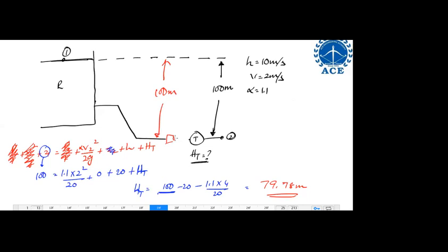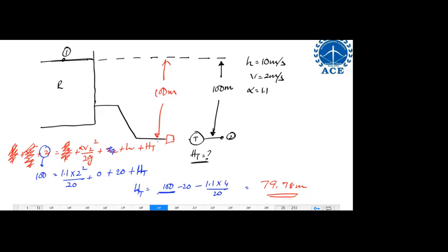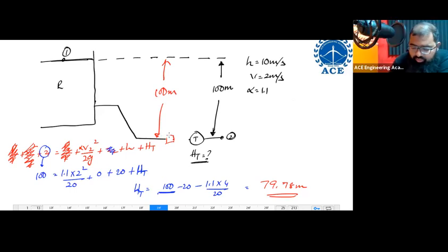Yes, sir. That is fine, accepted. But that is the net head available at the exit of nozzle, which is later going into the turbine. Okay? But right now he has not given you that particular case. Nozzle case he has not given you. He has straight away said that there is a pipe connected to the turbine over here. From the turbine, the fluid is exiting. This is what he's saying. That is, how much head the turbine has taken to produce power, he's asking you.